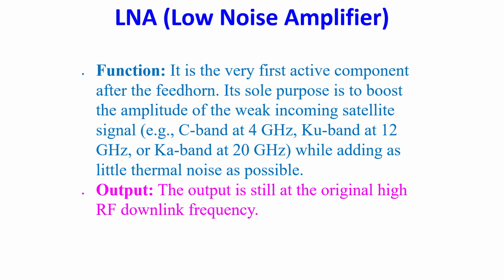LNAs are common in commercial earth stations, professional satellite distribution systems, or specialized amateur satellite setups where the amplification stage is kept physically separate from the frequency conversion stage to optimize performance and thermal management.